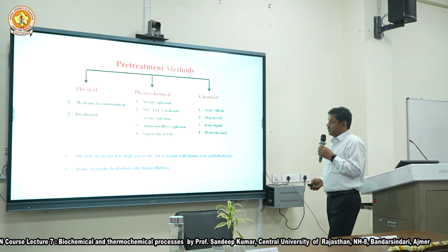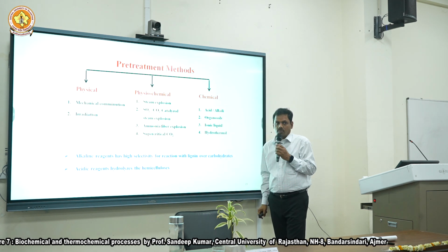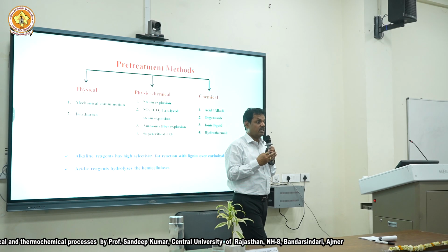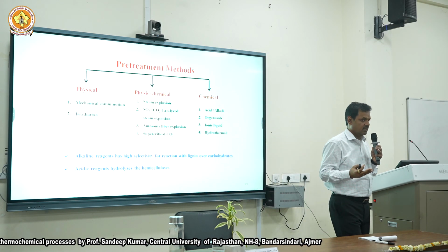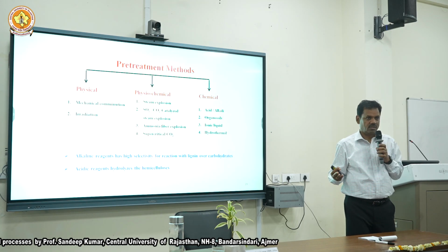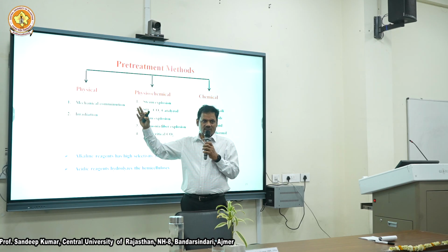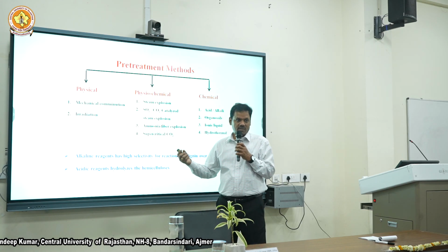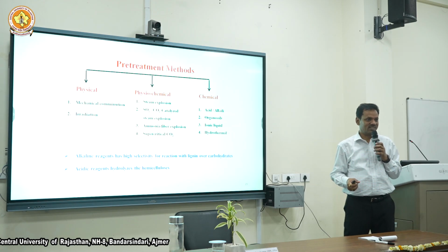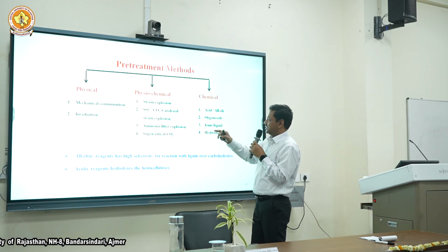So pre-treatment can be physical, physiochemical or chemical. If you grind well enough, grinding will increase surface area, am I right? Surface area means it's exposed more. You can do that, but this is power intensive. Right? We run grinders at home, it is kind of fun, we quickly switch it off because it's taking too much electricity, am I right? So it's like that. Can be a reason.